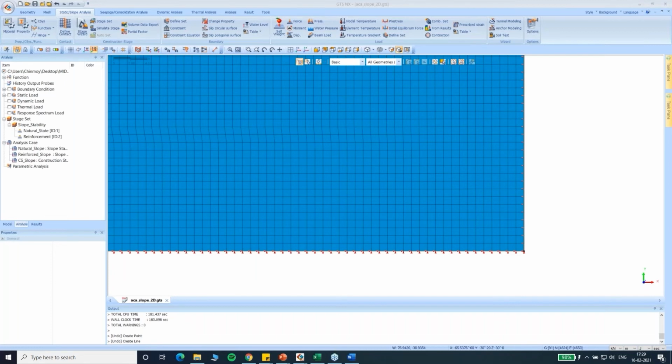A question asked by Lorenzo is that the element alignment is not something required in all FE software. It is not required in all FE software, but if you need to have accurate results for the forces acting on the structural elements, then you need to have them aligned. Normally, this is also required in other software too, depending on what kind of accuracy you are looking for.